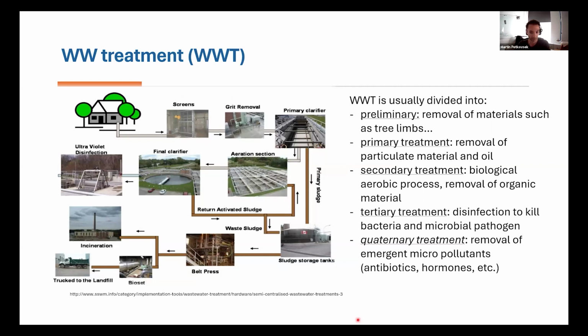For quaternary treatment, which involves removal of other micropollutants such as antibiotics and hormones, this treatment is currently under consideration to be put into legislation for wastewater treatment, because such micropollutants are only one part of contaminants of emerging concern, which we will present in the next slides.